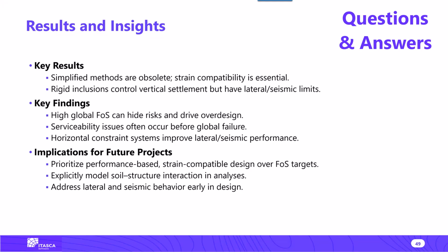And I also have the possibility to specify a different strength in compression and tension. A geogrid only reacts in tension and doesn't have any compression. So that's why with the cable element, I have the possibility to specify what kind of response I want from the element.